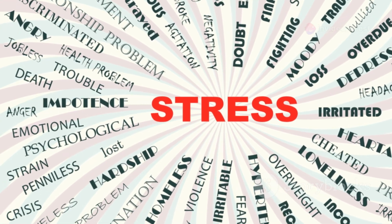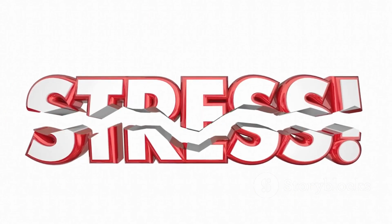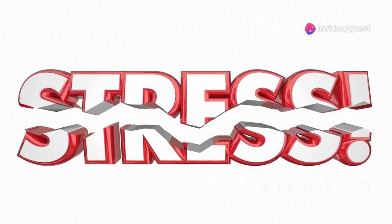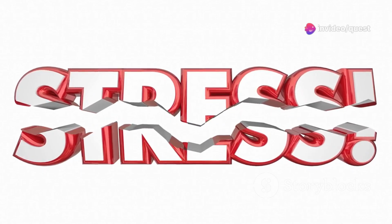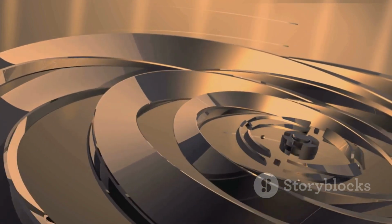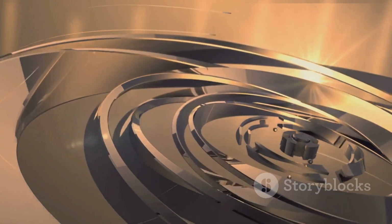The radius of the circle, on the other hand, is equal to the maximum shear stress. This tells us the maximum difference that can exist between the normal stresses on any two perpendicular planes in our material. Now consider the points on the circle's circumference. These represent the maximum and minimum principal stresses. They are the extremes, the highest and lowest normal stresses that a material can experience.